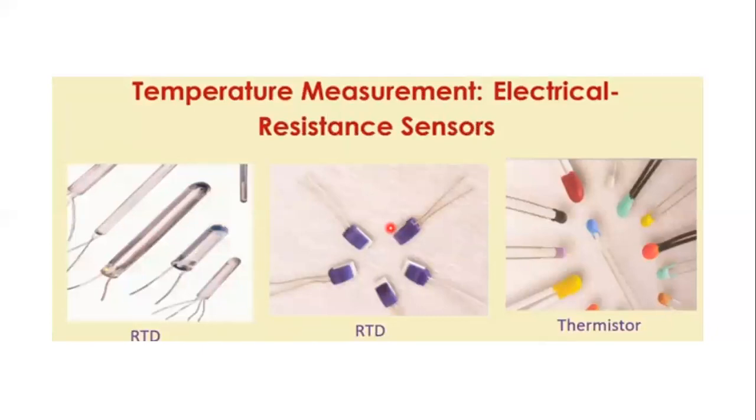That means when the temperature increases, the metal resistance will increase. The resistance of metals will increase with the increase in temperature. So metals exhibit a positive temperature coefficient. The temperature measuring instrument constructed from metals is known as resistance temperature detector, or metallic resistance thermometer, or RTD. So electrical resistance thermometers are of three types: thermocouple, RTD and thermistors.